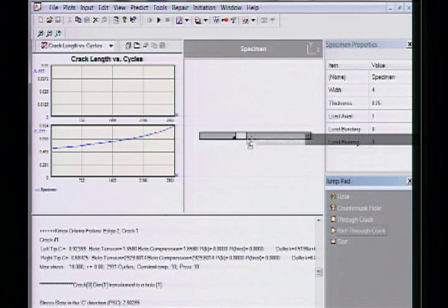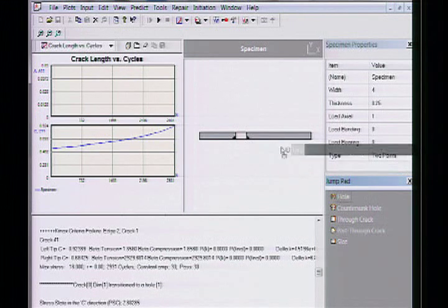The way this works right now is we can only have these corner cracks at one of the holes. But that doesn't mean I couldn't have another hole out here someplace that the one crack is growing towards. It's just that you couldn't have one corner crack on this hole and another corner crack on the other, because we just don't have that solution. As it stands right now, the matrix in here, these have all been solved by finite element models. So we have different crack shapes, different hole diameters, plate thicknesses, all kinds of combinations, so the matrix is quite large. To expand it to do any number of combinations of one on one hole, another on another hole, it starts to become unwieldy. But anyway, we can solve this problem as well.